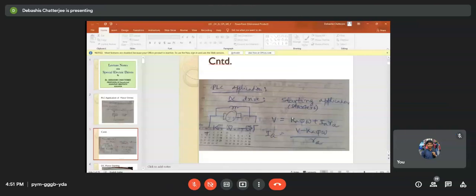The thing is that, say, when you see that DC machine or a DC drive system, now we have impressed voltage, and then the output is either speed or torque, right? And it takes current. So torque is K phi Ia. That means if you assume that the field flux remains constant, torque will depend on the motor current, right?